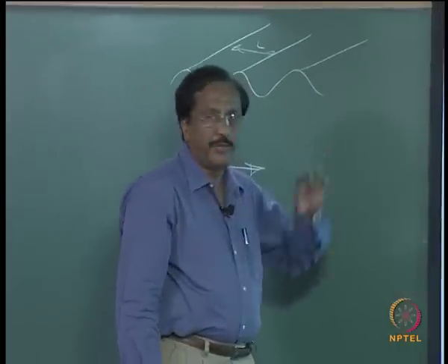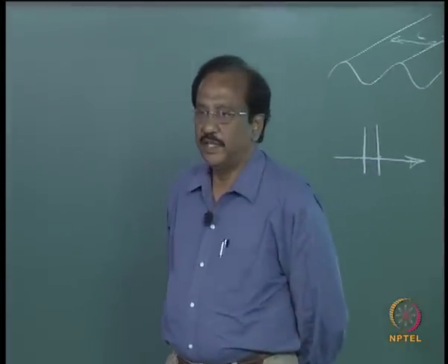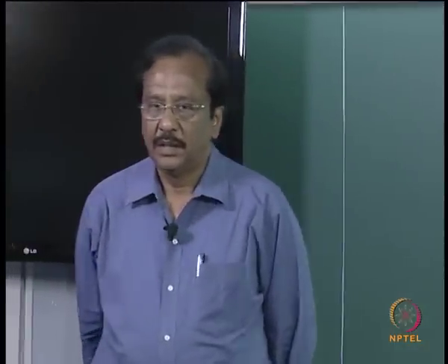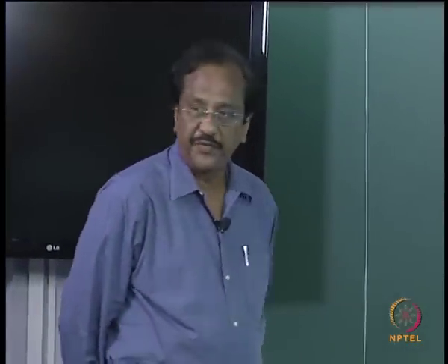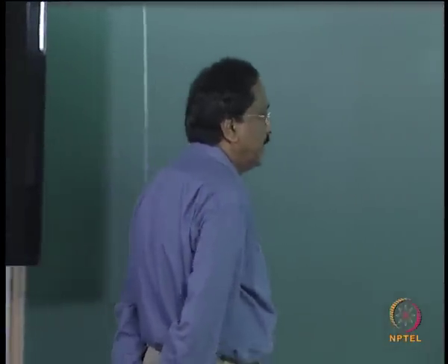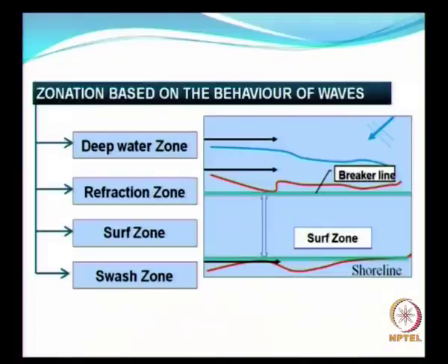So, the most important phenomenon takes place in the refraction zone. The waves start feeling the bottom as they propagate. The speed becomes a function of water depth, and this phenomenon is extremely important and also controls the stability of the shoreline.